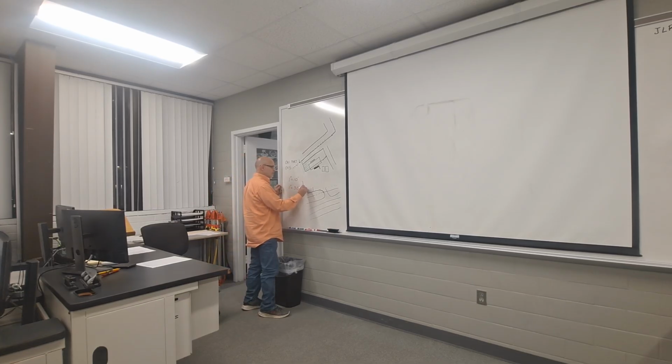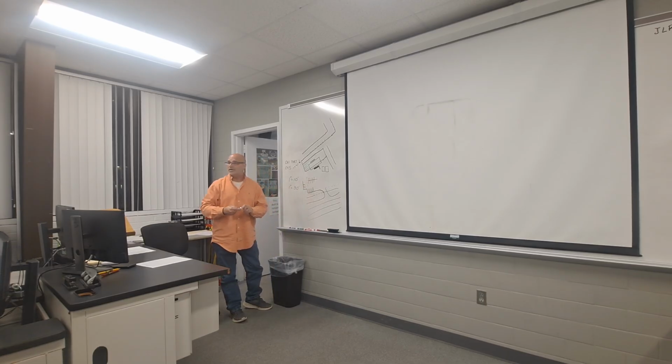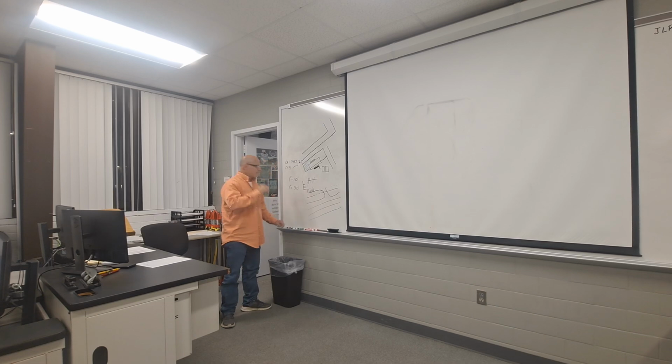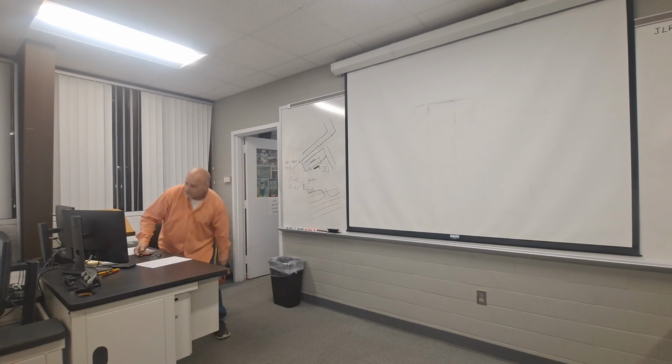So maybe you've got some parking spaces over here along this side. You got some parking spaces out here in the middle. If it says 30 feet between these two, it needs to be 30 feet. If it says 24 feet, I think is the minimum behind this parking space right here, 24 feet is what I wanna see. I don't wanna see a bunch of extra concrete. So I'll have students that'll go through and just make this big parking lot with just parking spaces right there in the middle. That's gonna be points off. So we're trying to save stuff like that, and reduce cost.